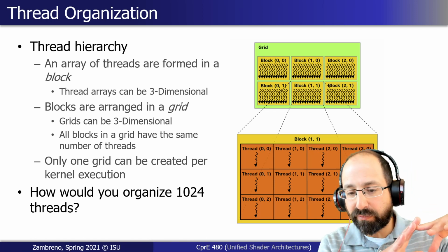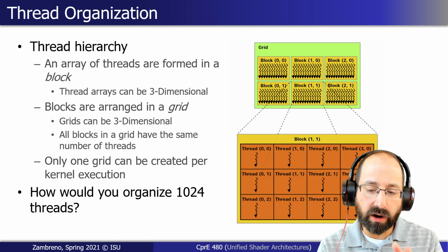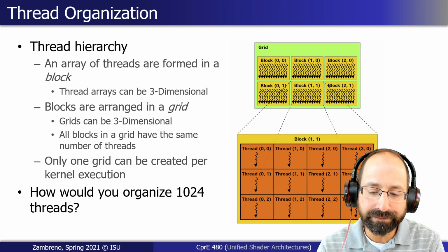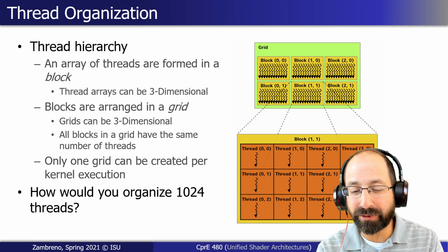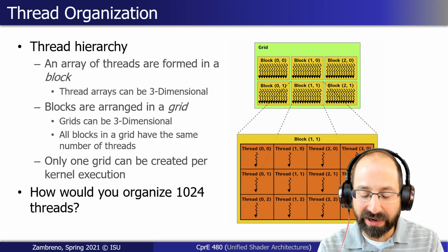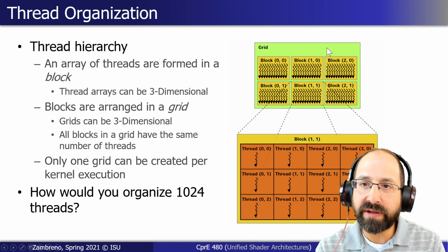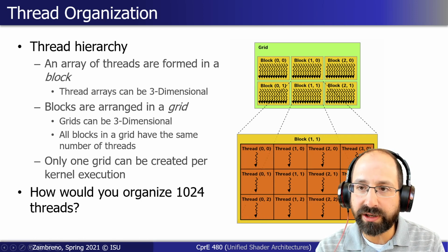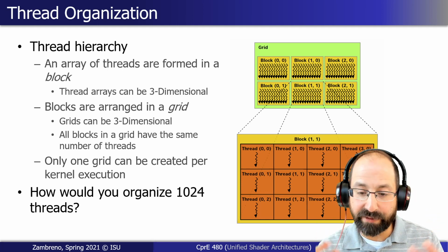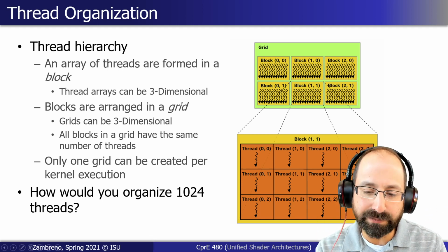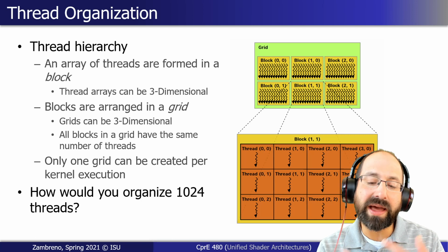And that next level of hierarchy is referred to as a grid. That seems arbitrary, but it's not. It's part of the architecture for how these devices are laid out. It's a little hard to visualize when we think of our simple GPU with just two shader cores. Once you get to a couple dozen, you have to think about hierarchy for organizing things. Part of the organizational structure is having this block as the individual unit of schedulable work. And if we have more work to do than that, we organize these blocks into grids in which those blocks are entirely independent of each other.